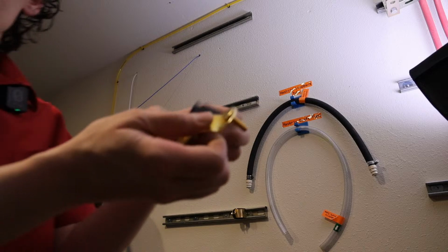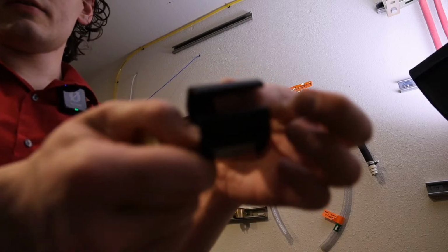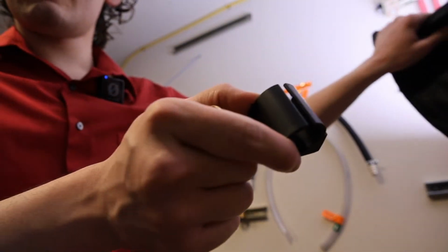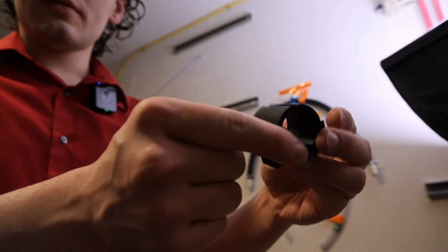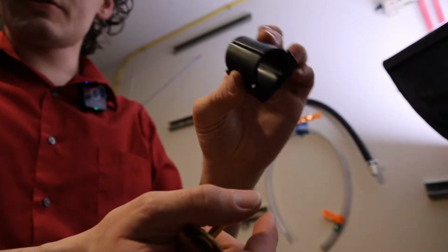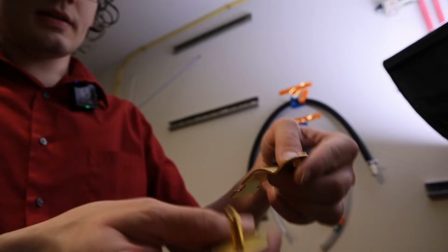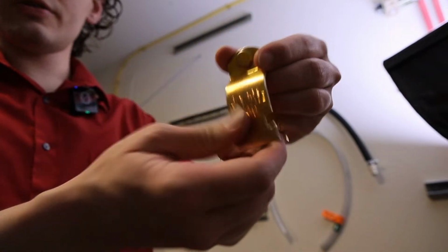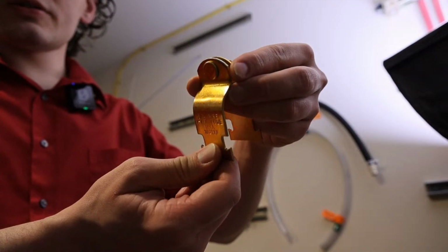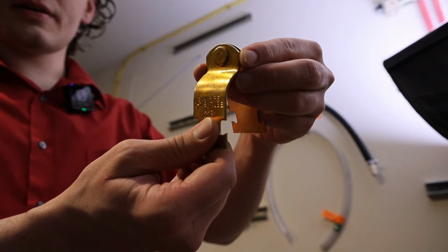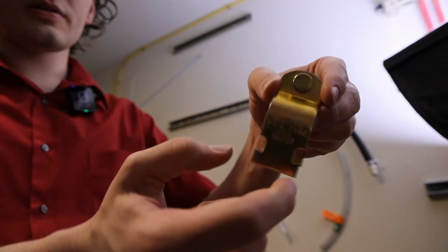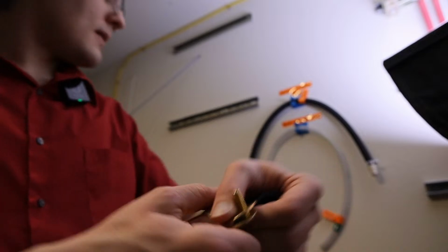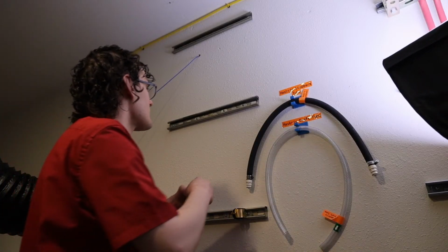These strut clamps are pretty cool. They've got this rubber part here. So this is what actually clamps onto our PVC. And then these two halves here go into the strut, and as you tighten that bolt on top, it kind of clamps down and pulls up and out on the strut, so that it digs into the strut a bit here to really hold it in. Okay, so let's get...